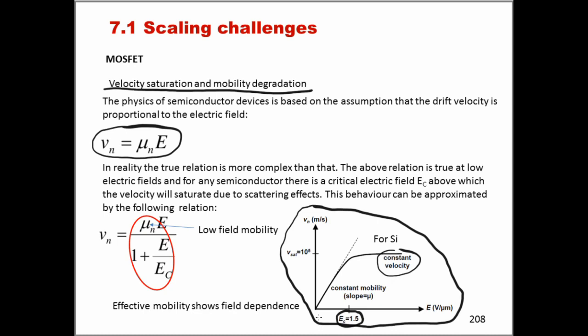in reality, when we are dealing with short channel effects, or there is a danger that there might be short channel effects, we need to use a different formula to relate the speed of the charge carriers with electric field. And this formula is the one that I've shown you here. This is a reasonable approximation of the curve that I've drawn here in this plot that has this saturated behavior here.